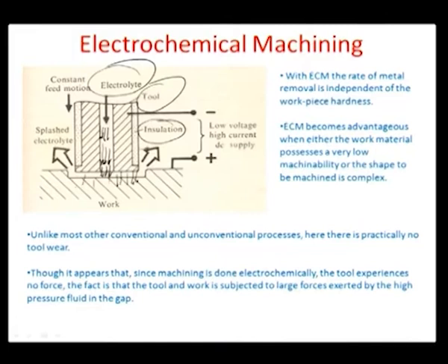And then of course, this tool should have constant feed motion, so there has to be precise control on the feed motion of the tool. And then of course, the electrolyte which is splashed needs to be collected and circulated back into the pumping system, so that the debris which moves along with it can also go and doesn't clog the very small gap between the workpiece and the tool.